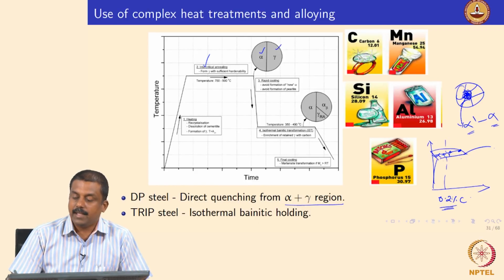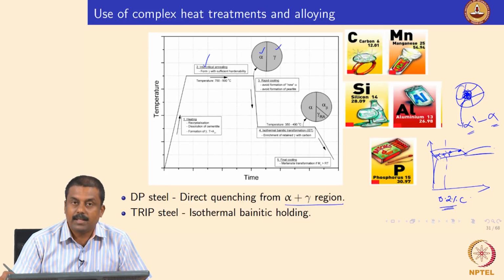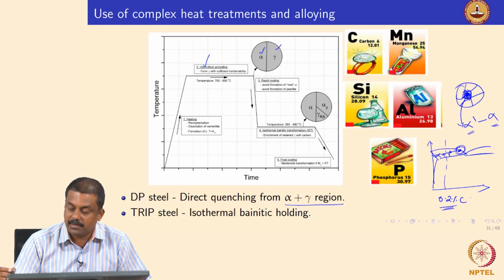To achieve this heat treatment, the critical metallurgical parameter needed is the carbon concentration of austenite. That is very critical, because in factory cooling rate conditions, we cannot really achieve high cooling rates like in a quenching heat treatment.